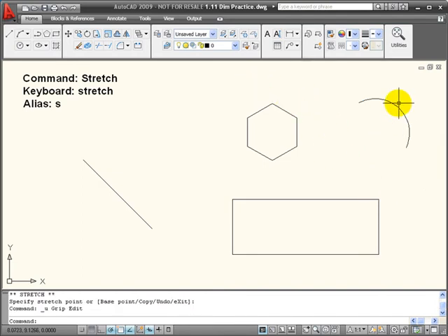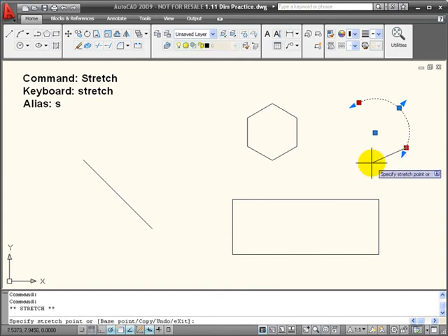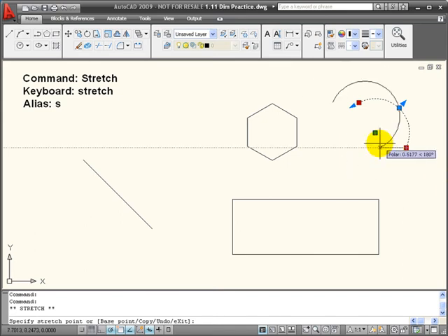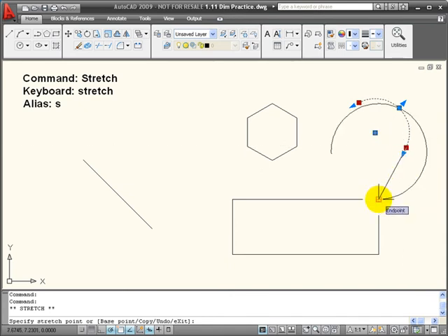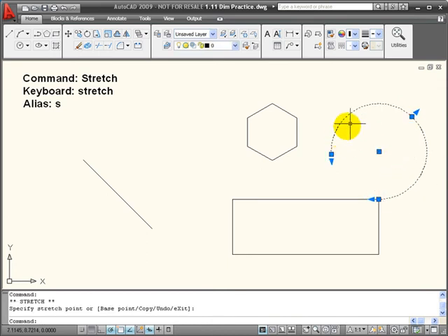Now I'm going to click on this arc segment again, and this time I'm going to hold down the Shift, and I'm going to select the two endpoints, and then I'll choose this end point as a base point. And now as I start to stretch this, you'll notice that my arc is stretched, but it stays consistent with that one unselected grip point as passing through the arc. So now if I come down here and snap the end to this endpoint, the only thing that remains of my old arc is the fact that it still passed through this same point.